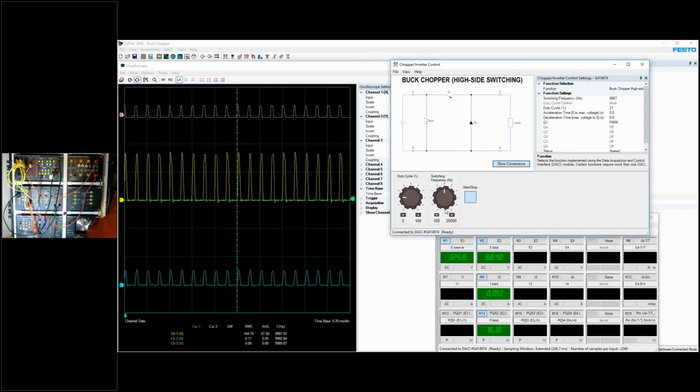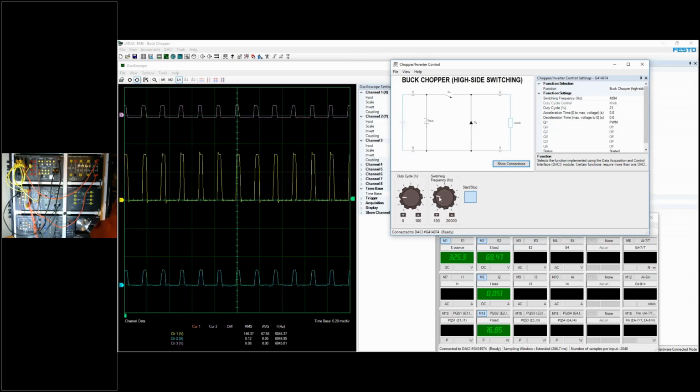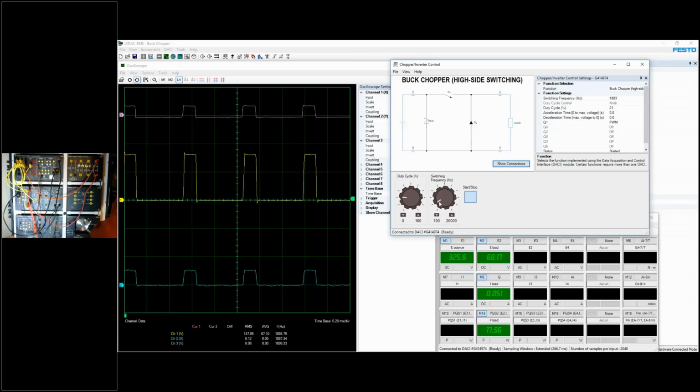And it's much more interesting for me also, because in my ears, instead of hearing the 1 kilohertz whining from the transistors, now at 10 kilohertz, it's more bearable. It's higher pitch and much lower in intensity. So you can see that that's what a buck chopper does. It simply lets the voltage through and the current through on a certain portion of the time.